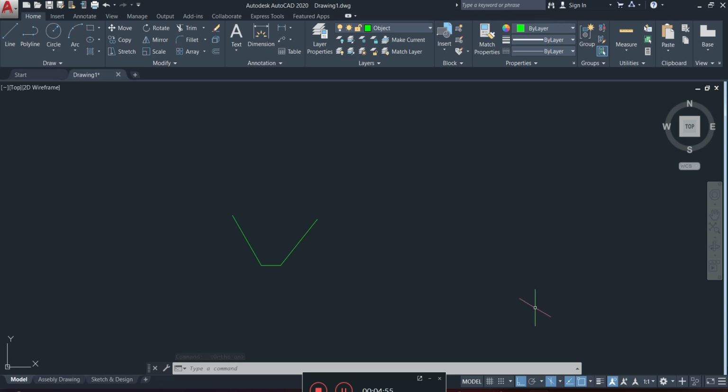Now, in your ISO mode, if you click on this drop down menu here, you'll see three different options. You'll see ISO left, ISO top, and ISO right. Alright, now I'm going to explain those shortly. Now these assist you in drawing each side or each phase or each dimension of your isometric drawing.